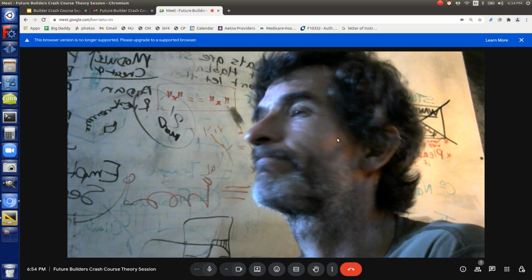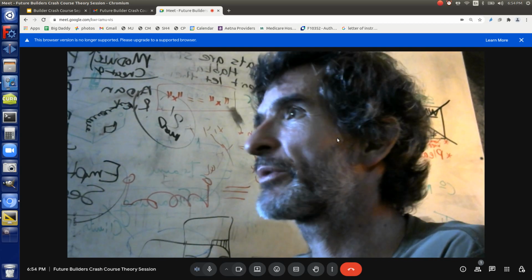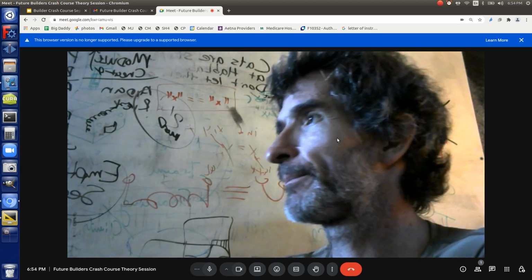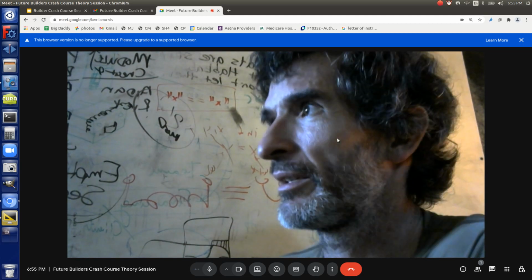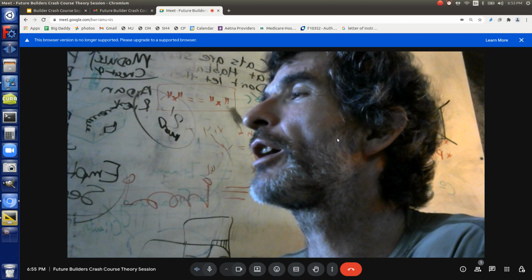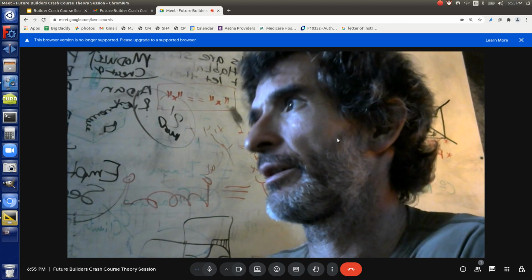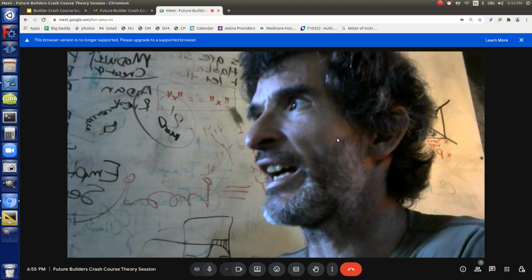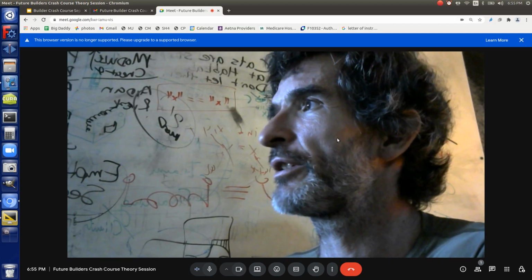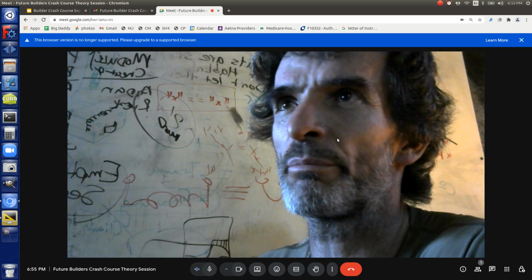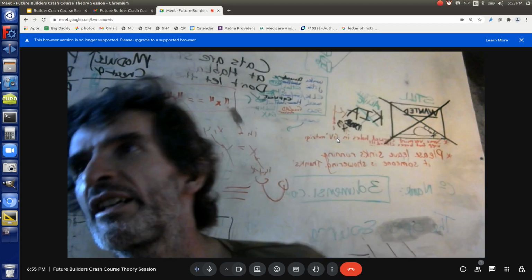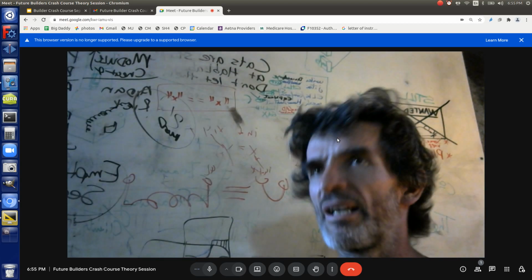Yeah. 1/8 times 1/8. The area. Area is not 1/8. It's 1/8 times 1/8. That's 1/64. Oh. So you're talking about about 100th of the value of steel. So if you had 100,000, 100th is about 1,000. That's when that nail is going to break. So you can start thinking along things like that for how strong things are and so on.